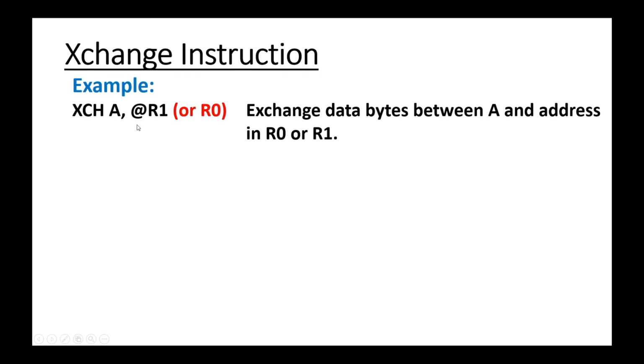Next instruction is XCH A, @R1. There are only two register pointer registers, R0 or R1. Between two, any one can be used here.